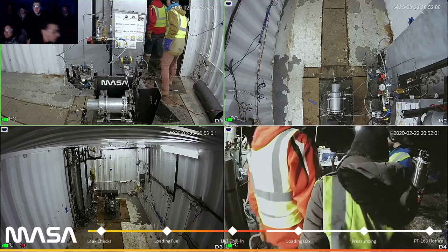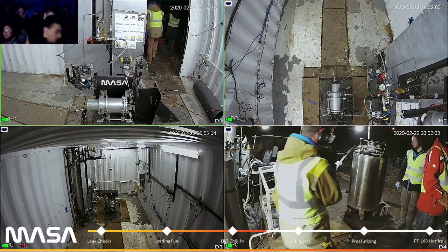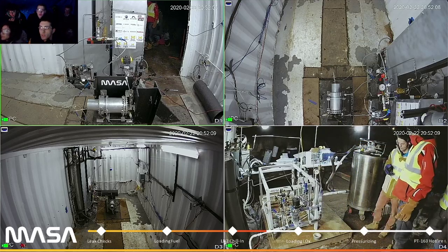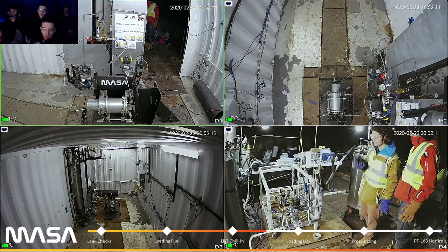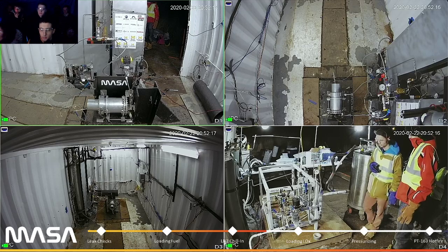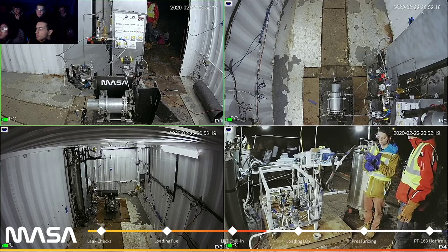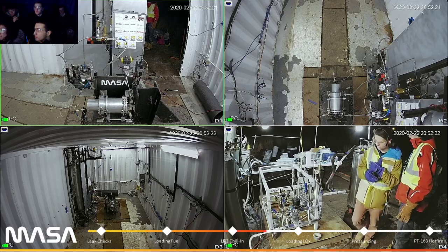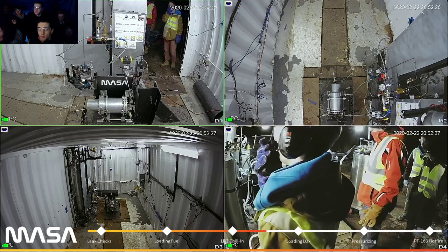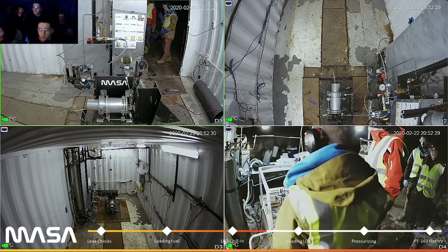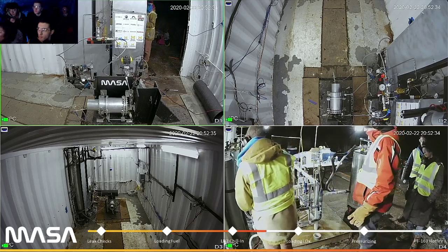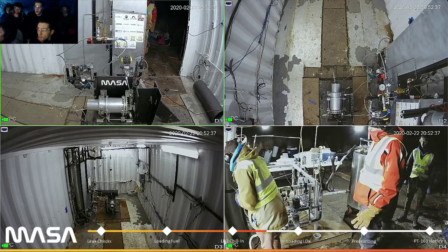And our igniter is made from APCP, right? Yeah, our igniter's made from ammonium perchlorate composite propellant, APCP. Do you want us to keep fill vent open in that time? Copy. Opening HES for 2 seconds in 3, 2, 1. APCP is what a lot of solid motors are made out of, but we have a much smaller quantity that we ignite using an E-match. We ignite the E-match, that ignites the APCP. It burns very furiously and fills the chamber with a hot flame. And then the main propellant valves open. Copy. Closing LOX fill pneumatic vent.